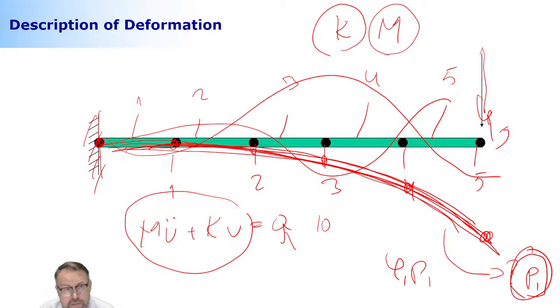And one of the misconceptions that I can see every now and then is that people are expecting that these deformation modes are something that is absolute deformation that actually takes place. No, you cannot tell that. Why? Because you need to know these modal coordinates to be able to tell that. So the mode itself is nothing but the way the structure deforms. Again, nothing but the way a structure can deform. And they are associated to frequencies.